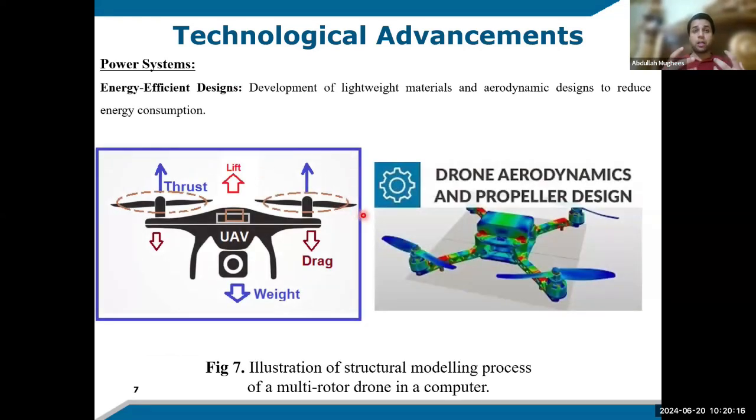the structure of the drone matters a lot. Well, we have the engineers. What the engineers do is consider the thrust forces, the drag forces, and all of the aerodynamic effects, and they simulate it and define the material that will be used, and then they see what pressure it can withstand, and in what conditions, what the behavior of this body will be. If the motor is rotating at this speed, it will generate this amount of newtons of force at this instant. It should not break the arm.